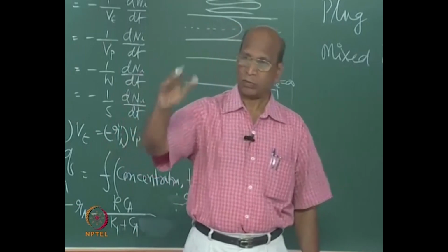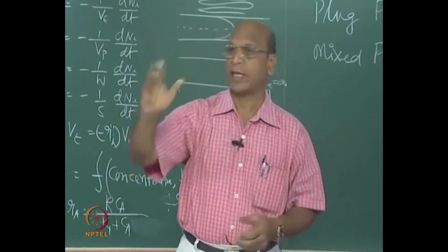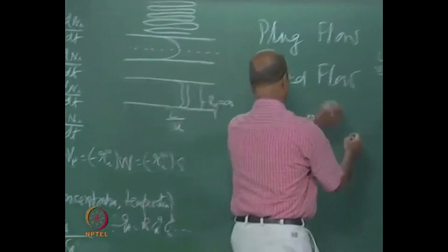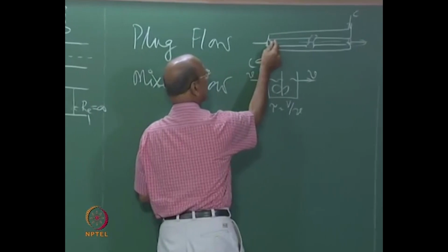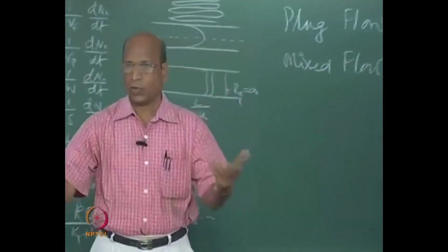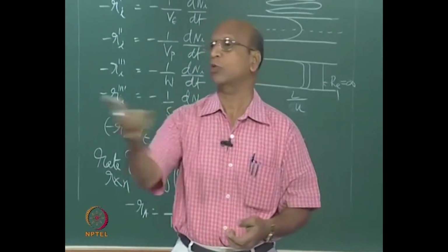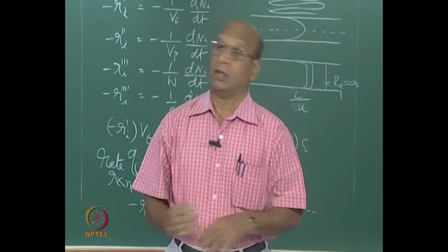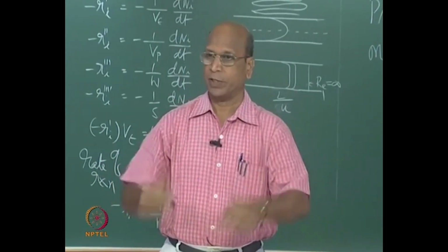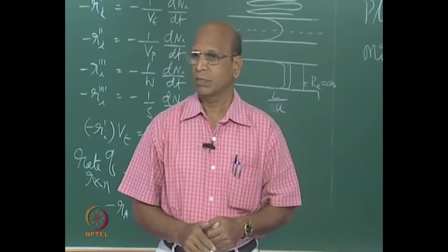You can have it theoretically in your mind, if you have an infinite number of heat exchangers. So, that means I will put one heat exchanger here, one here, one here. Almost every 1 mm, 2 mm, if you put one heat exchanger, probably you may get almost isothermal. And will you design so many heat exchangers, so many feeds, so many outlets, so many pumps? No one will do. Okay?